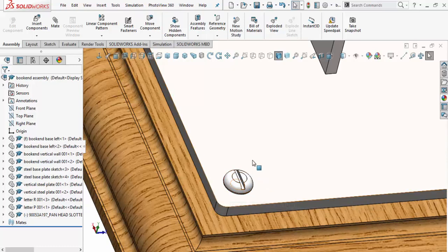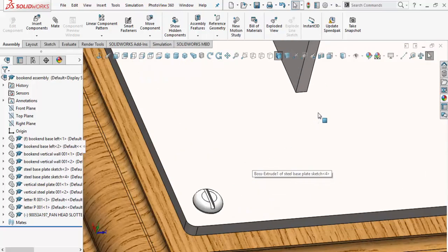So the way we do that, again, this goes back to one of my laws of how I like to design, is you always design to the materials and the tooling that you have. Well, one of our tools are drill bits. So we can bore the size of that hole out even further if we knew what the next size was to bore it up to. The only way we're going to know that is we're going to have to do a section cut.